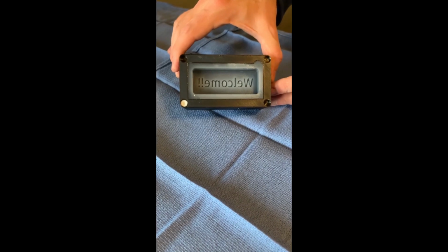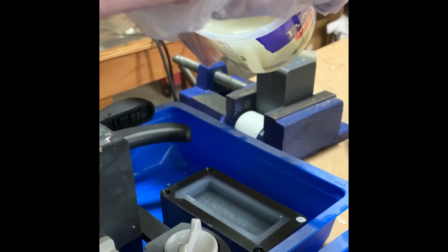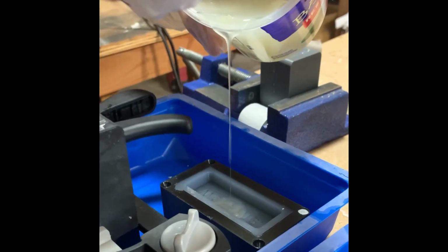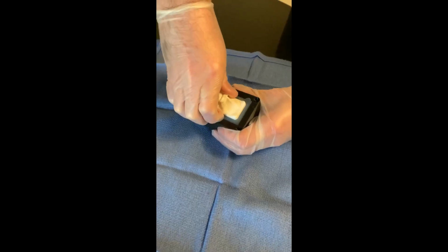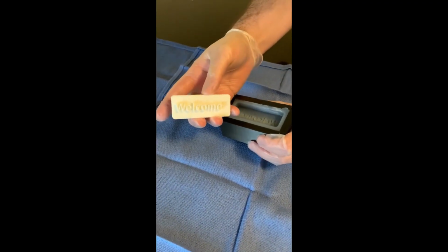You pour in the resin, wait for it to cure, and then pull it out. Pretty simple. This is the simplest, cheapest mold, but it's a good choice for a lot of parts. The downside, though, is that the back side is just open to air, so the resin may not cure perfectly flat, and it's really hard to get an exact thickness. So if you care about that stuff, then you want to get a two-piece mold.